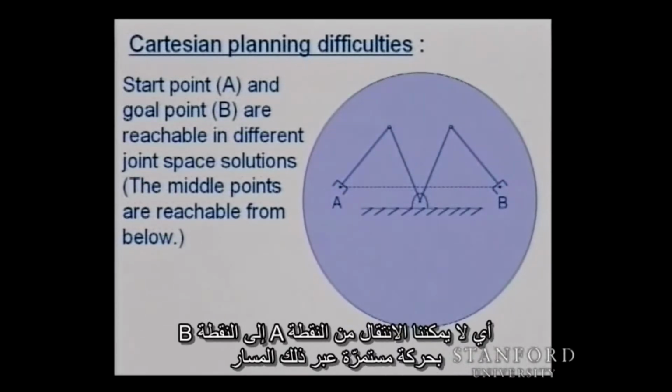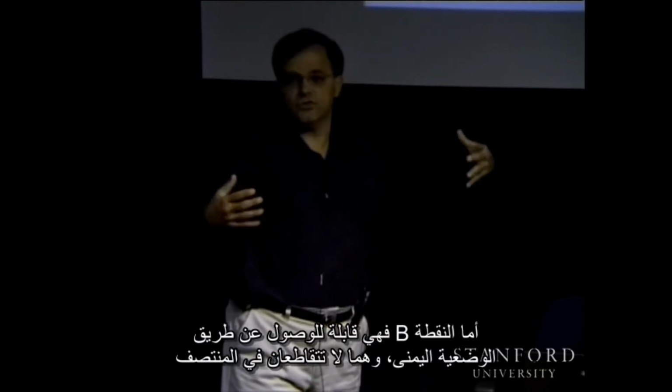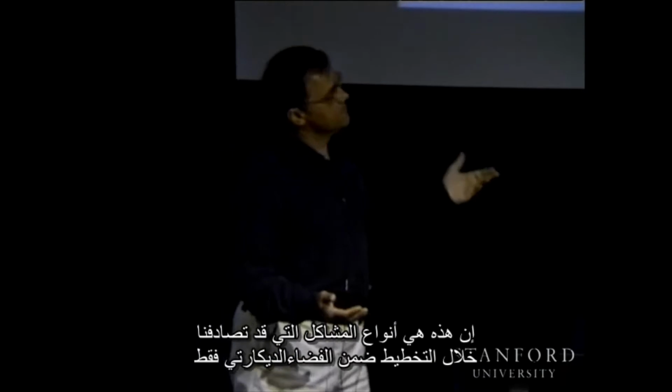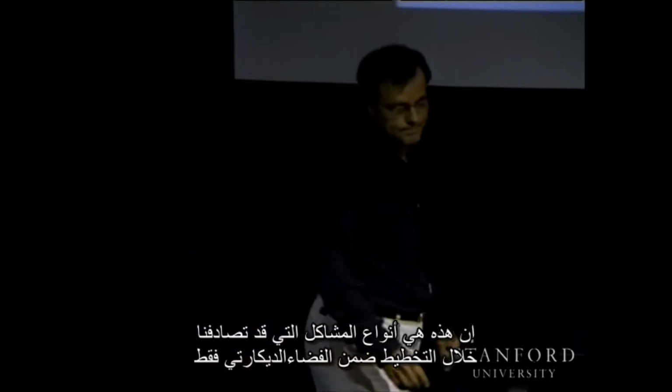So we cannot go from point A to point B in a continuous motion along that path, because point A is reachable from the left configuration if you want, and point B is reachable from the right configuration, and they are not intersecting in the middle. So this is the type of problems that we can encounter when we are planning in Cartesian space only.